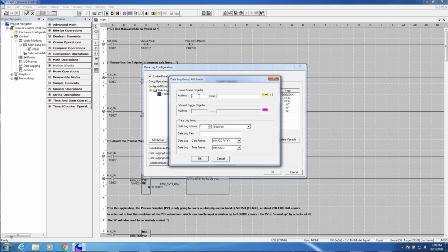Well, when you go and actually do data logging at runtime, so when the OCS effectively starts gathering data and then writing it to the memory card in the CSV format that can later be pulled into a spreadsheet, for instance, it's going to first read the data to be logged into a RAM buffer. And then it's going to accumulate data, and then at some point, periodically, it's going to write that data to the memory card. Now, if somebody were to pull the memory card from the OCS, well, obviously at that point, the data can't be written to the memory card.